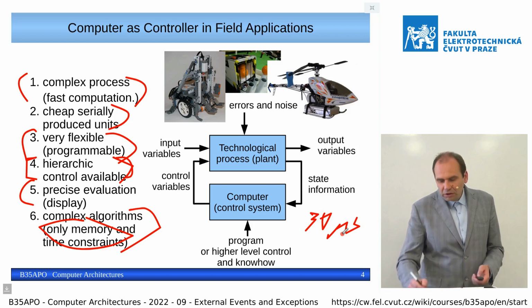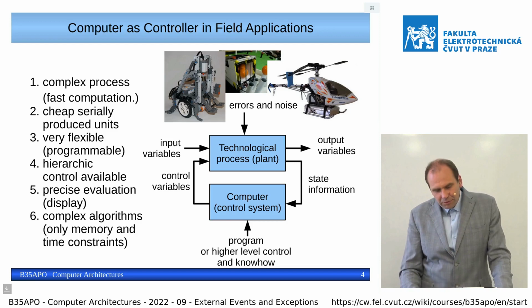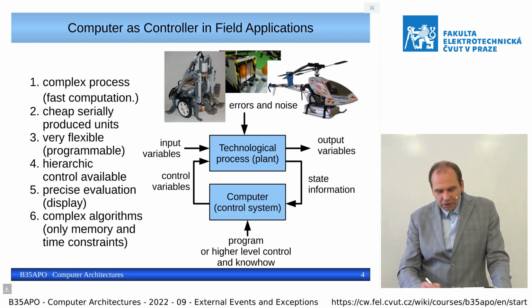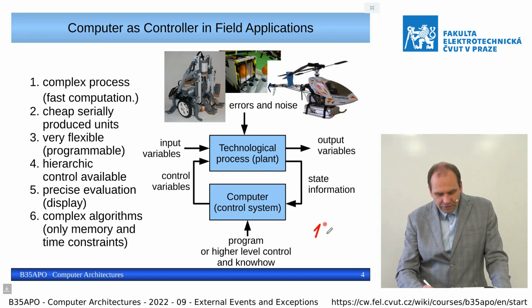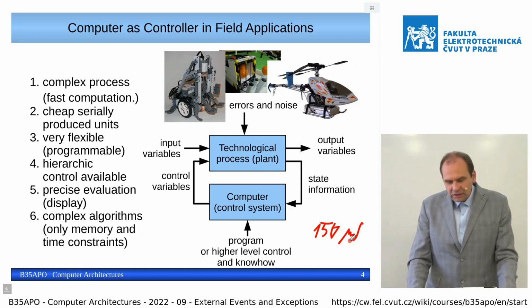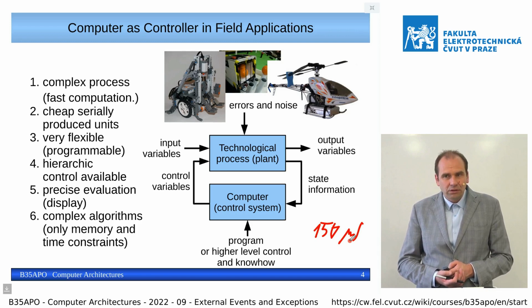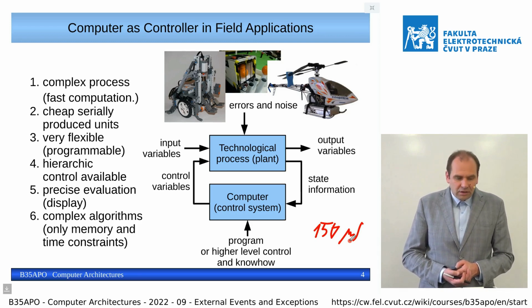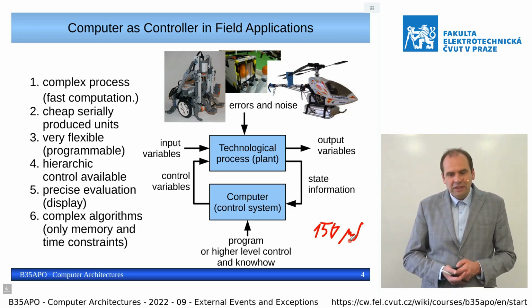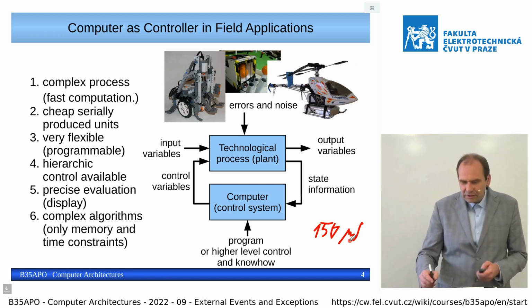On smaller ARM-based processors, we get something like 150 microseconds maximum latencies, so something like 5 kilohertz control with our, for example, MZ Apo boards or other hardware is possible if you have a real-time kernel.